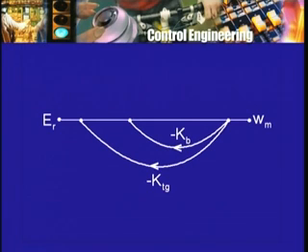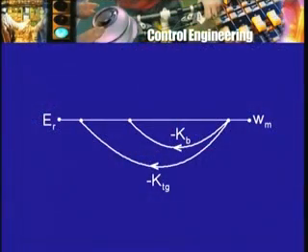And so we have a block diagram or a signal flow graph in which we have two loops. I told you earlier that in many cases the control system arrangement will result not in just one loop but two loops. But in this case, this loop that appears to come because of this Kb is not a physical loop. There is no physical signal being picked up as Kb omega m and connected to some difference device at all.